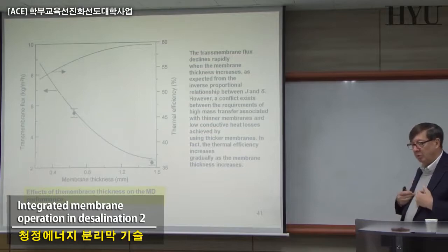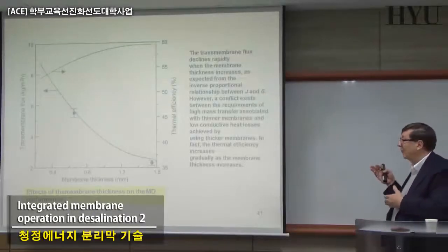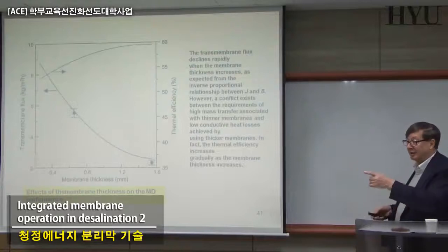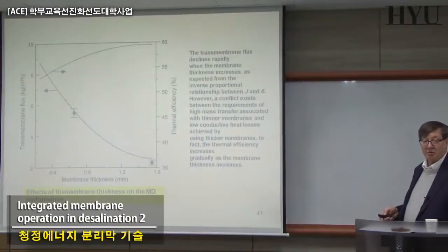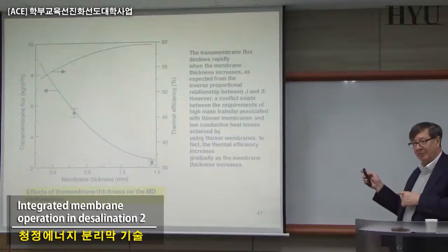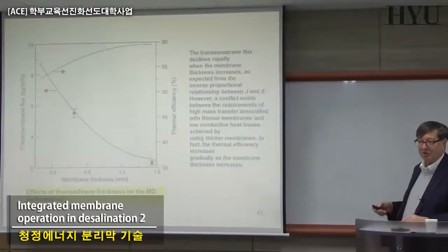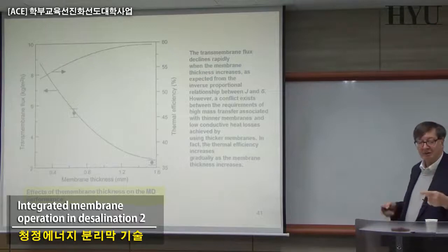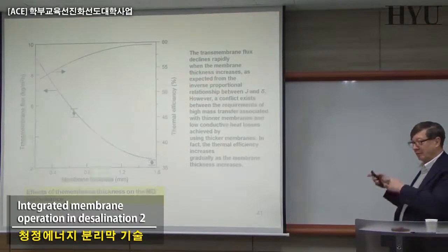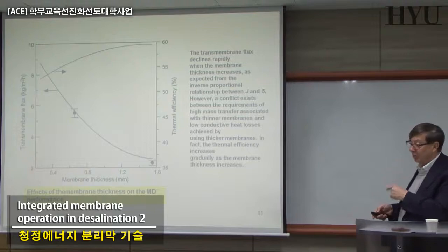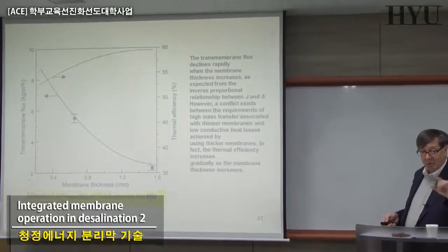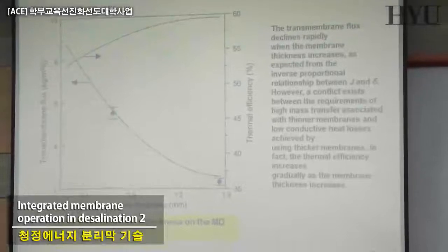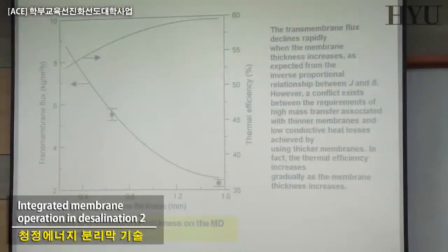Today, the membranes we are using have not been designed for membrane distillation. They are traditional membranes for microfiltration and ultrafiltration, adapted to membrane distillation. We have to redesign these membranes and produce, specifically for MD, the membranes of tomorrow, in which the thickness will not be the same as we use in ultrafiltration or nanofiltration, because in terms of flux we eventually increase, but in terms of thermal efficiency we can decrease the efficiency.